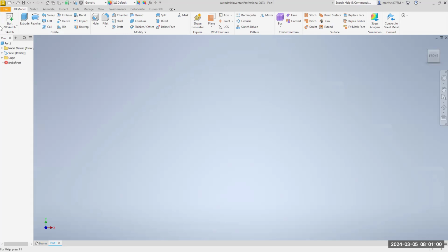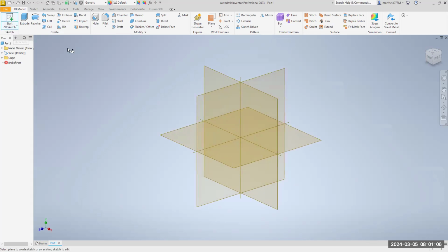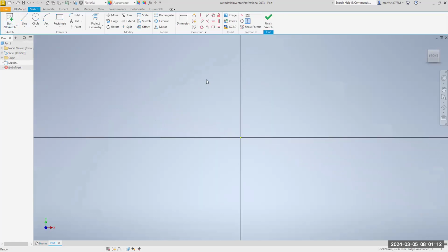All right, we want to start 2D sketch, and we're going to click on the XY plane. Millimeters. Now, believe it or not, the way we're going to do this is slightly different than what you might expect. So what I'd like for you to do is go to circle and select circle center point. I want you to come down here to the origin and click.